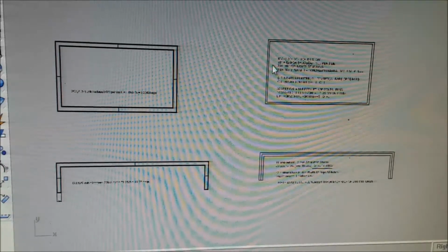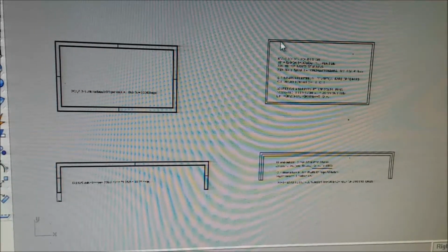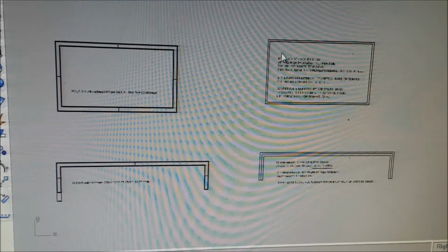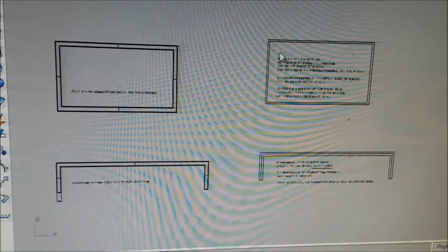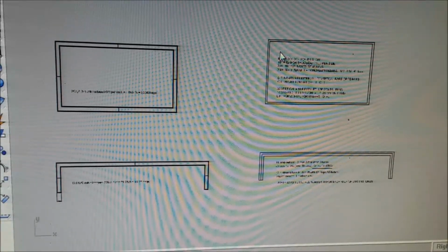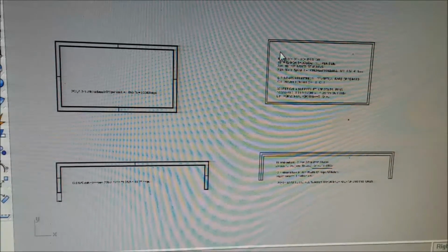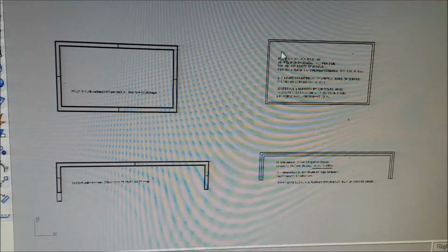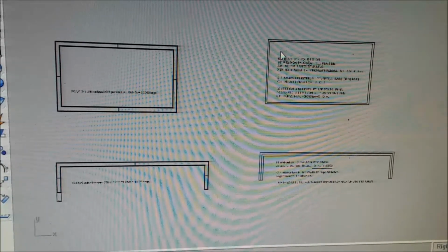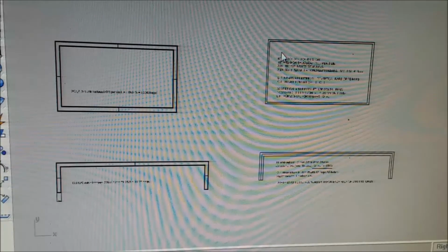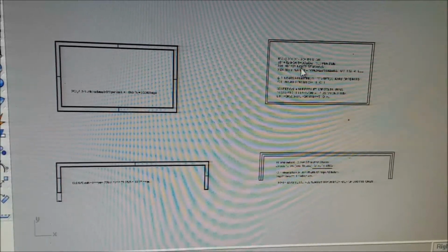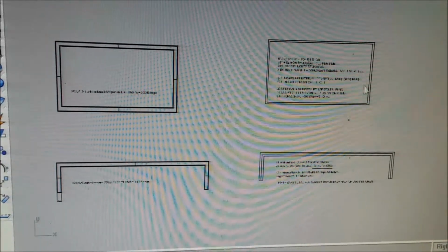And it's like a floor. If I was pouring a floor, and I have a column in here, and the floor is poured up to the column, well, that's going to give me an inside corner. They're unavoidable, but they're also a very bad thing. They're going to run a crack. You get a stress concentration with the heating and cooling of the day, and that inside corner is going to run a crack, sort of perpendicular to the corner, like a 45-degree angle crack. It'll go down here, and then it'll turn the long way of the slab. And you get them at all 4 corners.